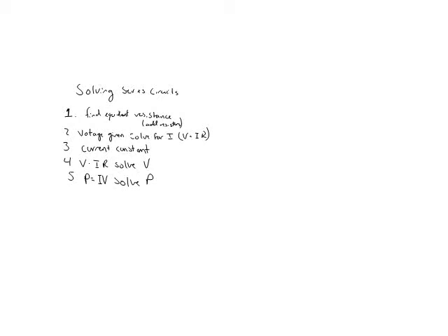So you can see we have 4 resistors here. And because they're all in series, we have one wire connecting each one of them, one full loop. We can just add those resistances together. So we get our equivalent resistance. That's the step 1 that's up here. So we're pretty much just dealing with one battery and one resistor. That's what they mean by equivalent resistance, or total resistance if you want. Because you're just taking the circuit and you're trying to simplify it so it doesn't look so nasty. Again, this isn't very nasty, but it will get nasty. I promise. It's like a big puzzle.